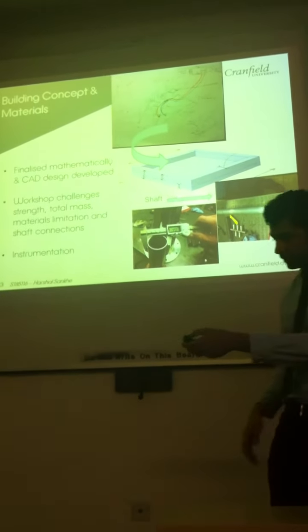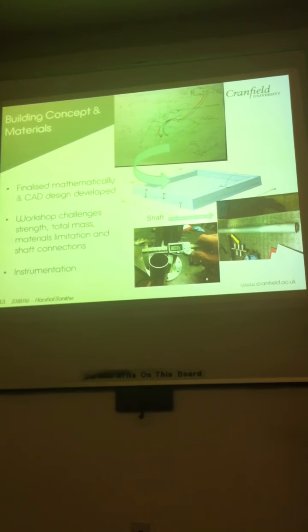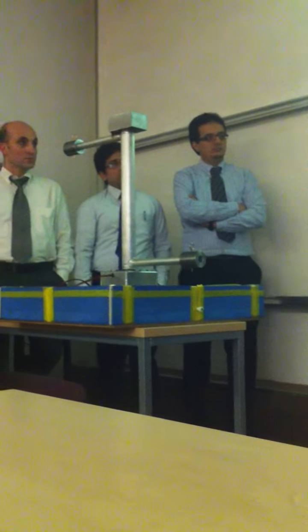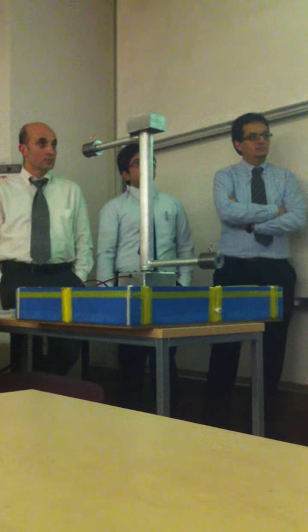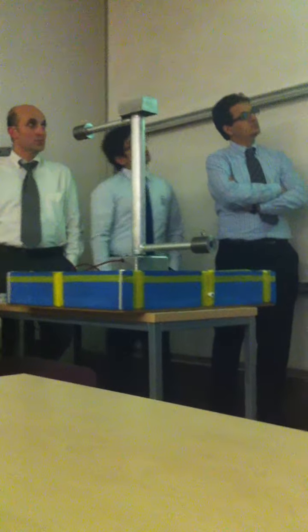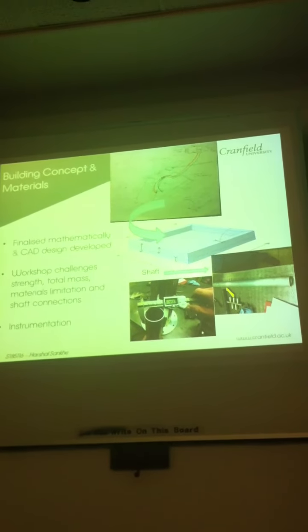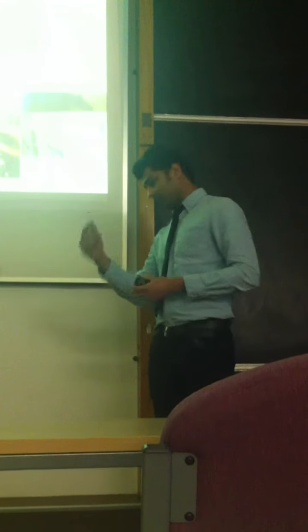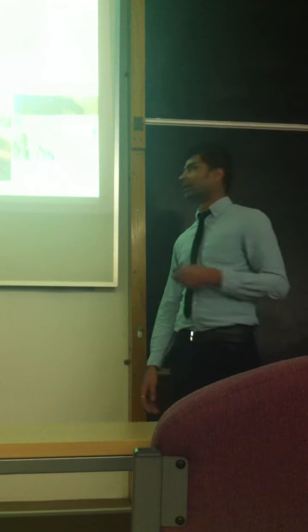There were certain challenges in how the concept started building up for this aluminum casing. Remember the pod, which was designed by last year's student for cultivation? The base isn't that strong. It's got only 4mm plywood over here. So we had a challenge to come up with a casing with good strength so that it can take the centrifugal and overturning forces which will act when this rotates at 113 RPM.